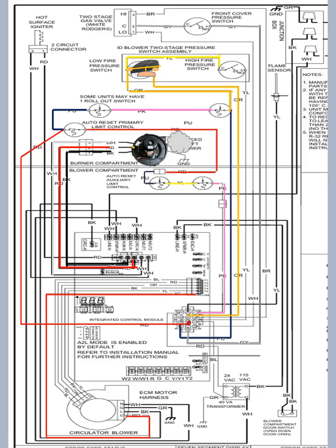The gas valve common is now closed. So that proving step, the pressure switch closed, the low fire, now we've proven that the front cover pressure switch is closed. We now have a path back.